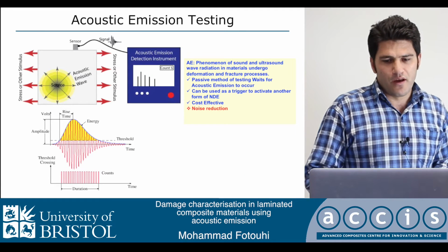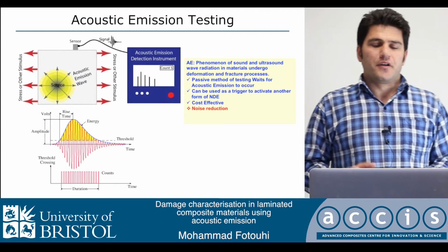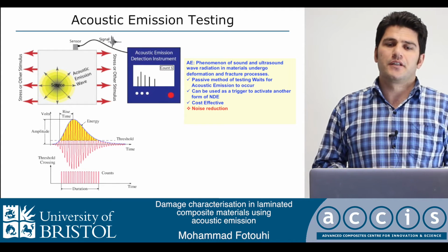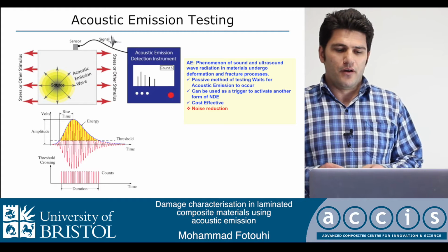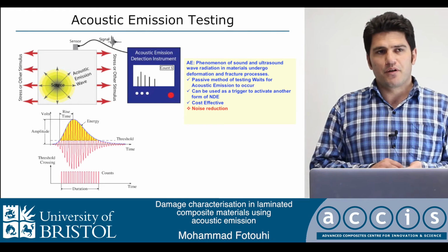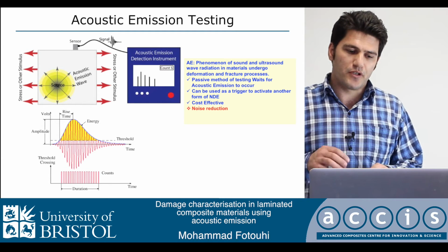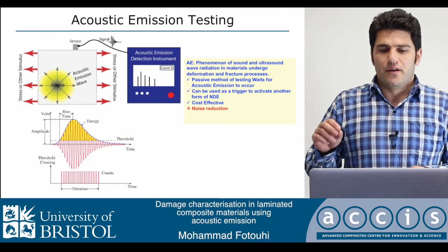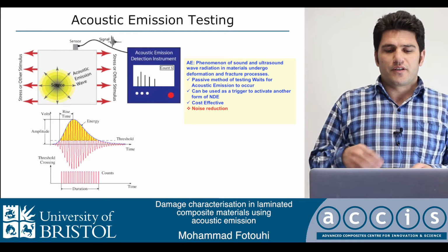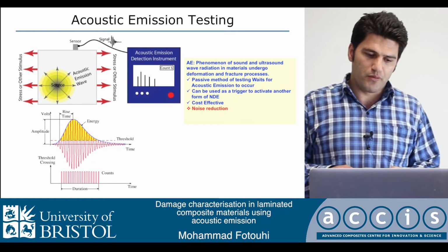Acoustic emission is a technique which is passive. It means that we just put our sensors on the surface of the specimens, and when we have a damage mechanism inside the material, we can catch the sounds and the waves produced by damage mechanisms inside the material.